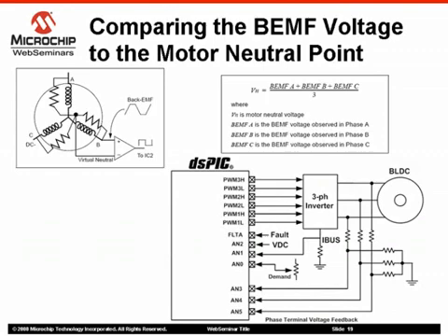The challenge of this method consists of determining the correct time where the back EMF signals should be sampled, since the samples acquired by the ADC may be affected by the resonant transition voltage caused by the PWM switching frequency. These samples may also be affected by kickback currents produced by the windings de-energization.